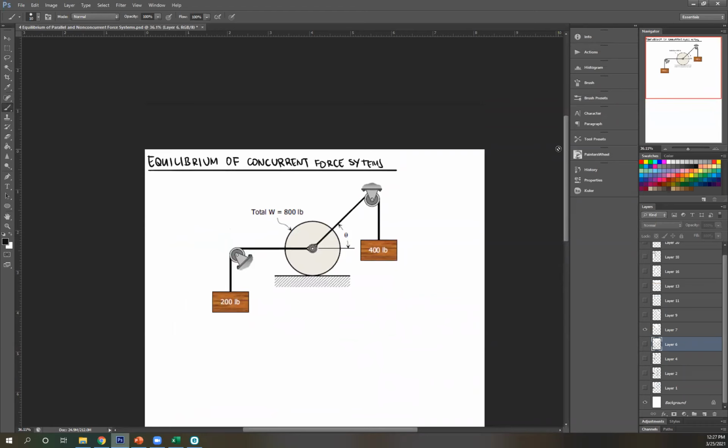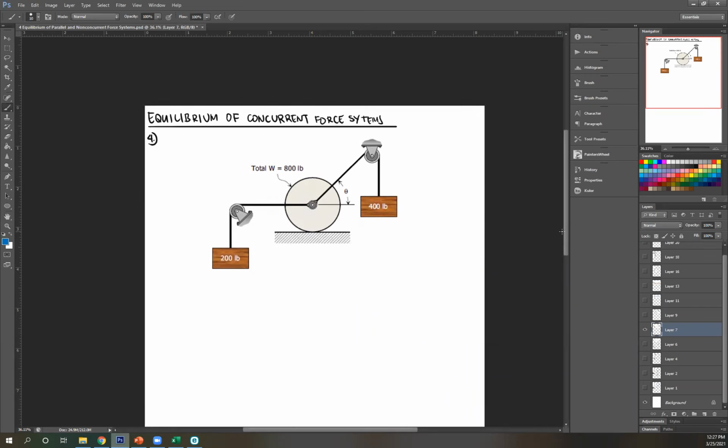So first things first, let's analyze what's going on. This is your cylinder resting on a surface. Once again, whenever you have two objects in contact, there is a normal force between them. So let me just draw our free body diagram here. Normal force is towards the object and perpendicular to the surface. So this is my surface, perpendicular to that, normal, and then towards the object. So it's upward. So in your free body diagram, you have two choices. You can draw it this way. Right? This is your point. Or you can draw it this way.